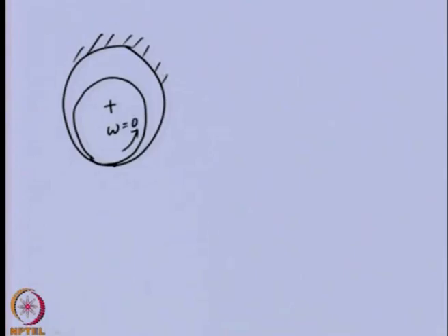But when the speed increases, the fluid which is in the clearance will try to go into this wedge, and because of this the pressure will be generated at the wedge, and this journal will lift inside the bearing.